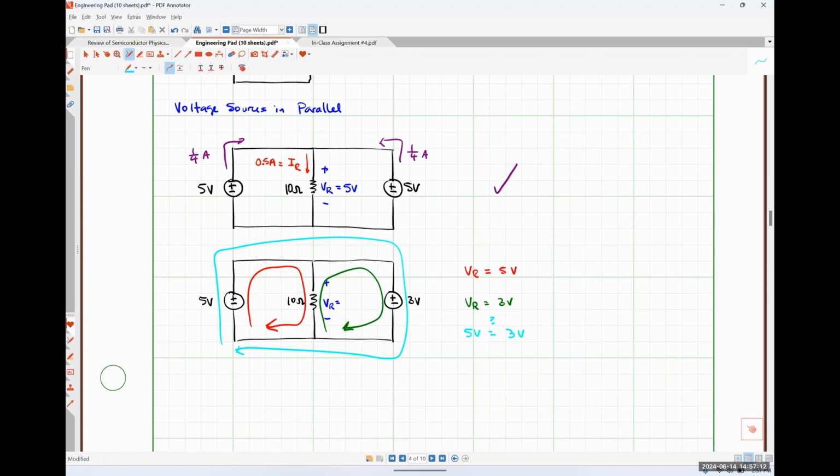What would happen is that the resistance of the wires would effectively be trying to take up that imbalance. So realistically, a very, very large amount of current, probably about as much as the battery could possibly supply, would wind up flowing through this section of wire right here and make that 3 volt battery incredibly hot because it's effectively trying to be charged up by that 5 volt battery, and there's not a lot of resistance to limit the amount of current that's flowing into it. Okay.